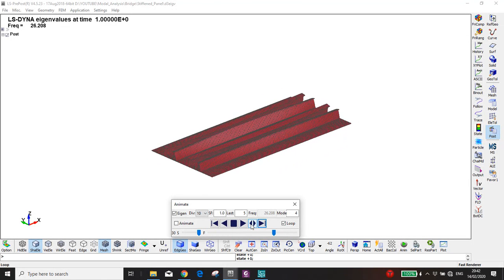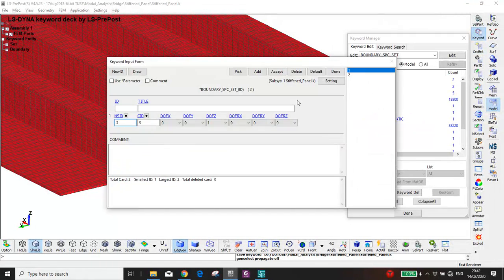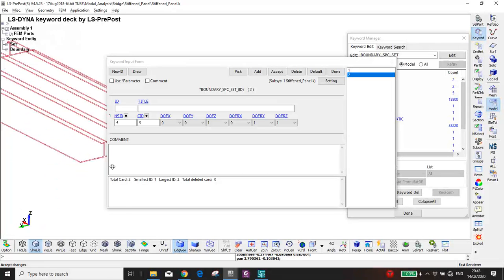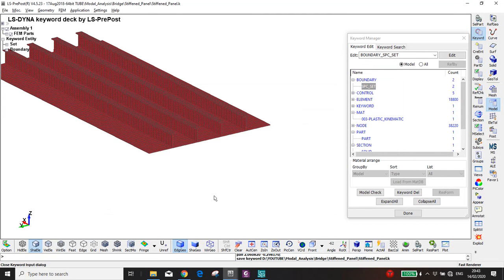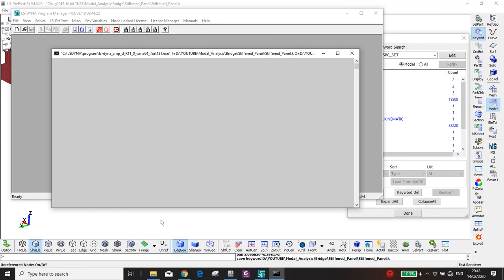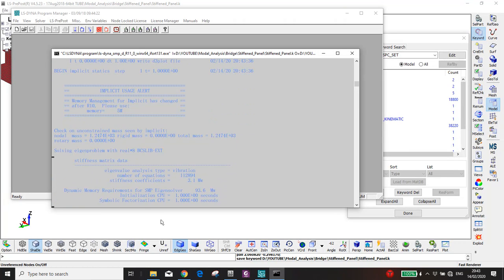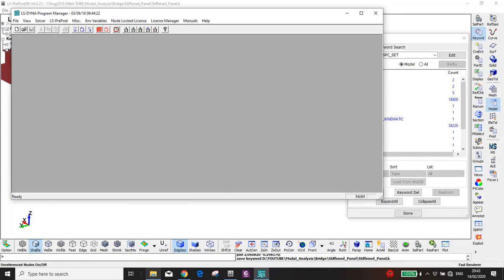Yeah. So here, can we just modify from here? Yeah, need to fix in Z and in Y. So the first part, this part cannot move axially like this, so it's fixed in X. And number 2 is these sides cannot move in Y. Okay, now we save. Done, saved. We close this first, then we rerun. And it's done. Now we go to this file again.